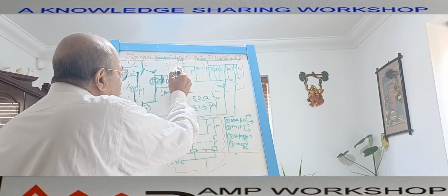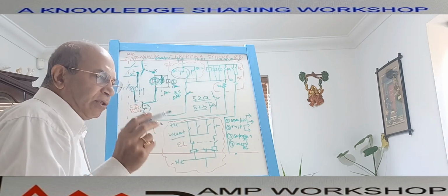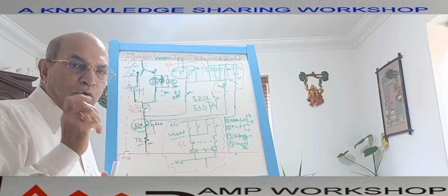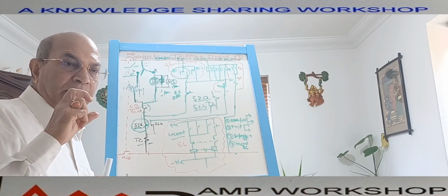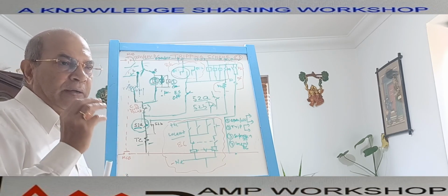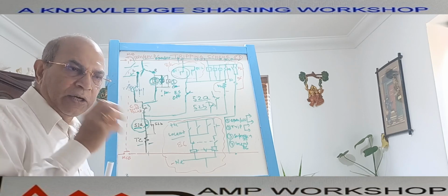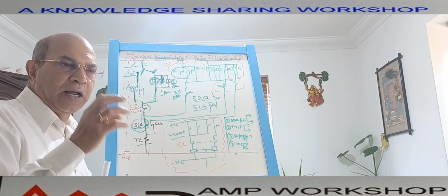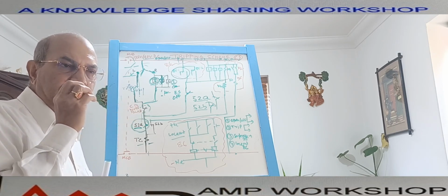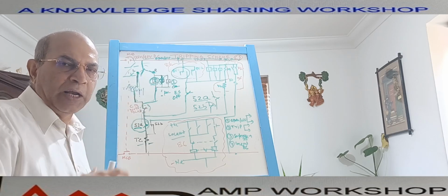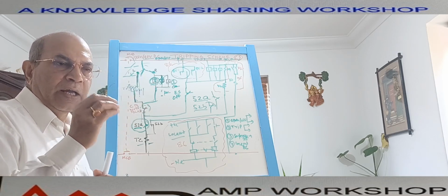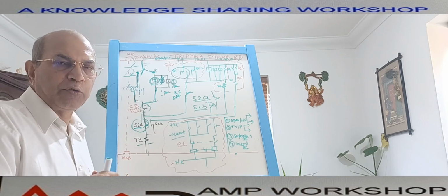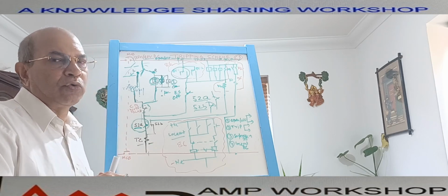This is what we call 86. Now this digital relay output contact, as I said, is not high rated, it is a low rating contact, and we need some interlock. What type of interlock? The moment the fault takes place, the fault is sensed, and the digital relay recognizes the fault and gives a tripping command to the output relay. Now the output relay of the digital relay we are not directly wiring to the tripping circuit.